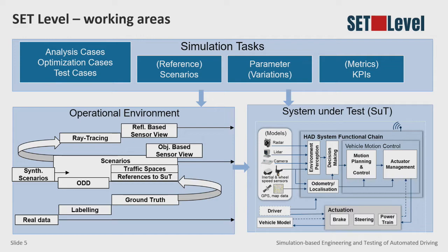And this is a translation step from the ODD, which must already be specified within the requirements for future products like an automated driving car. Scenarios can not only be based on real data, they can also be created synthetically, and they can be used to deliver the input which is required by an object-based sensor view on the right-hand side to analyze, optimize, or test an automated driving subsystem.